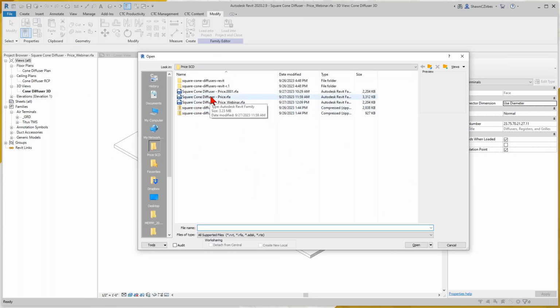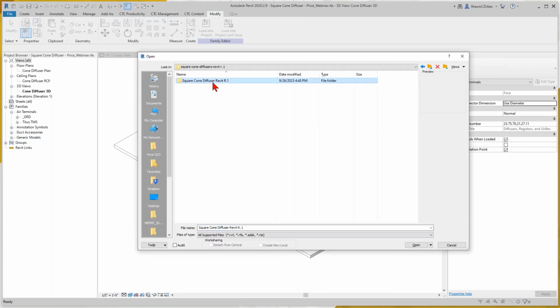I'm going to open this up. I've already downloaded from the manufacturer their latest version of this family. This is in Revit 2020. They have 2. One is a return, one is a supply. The only difference with the 2 that I could discover is the connector configuration. It looks like they took one, saved it as, called it a return family, and then changed the connector data to be a return. Makes perfect sense to me because there really isn't a difference. All it is is airflow direction. So I'm going to be focusing here on the supply family in today's little example.